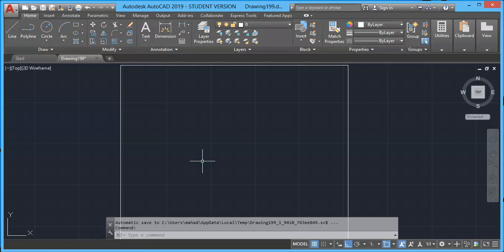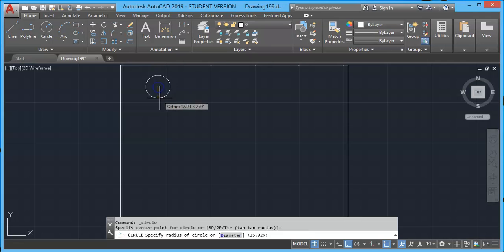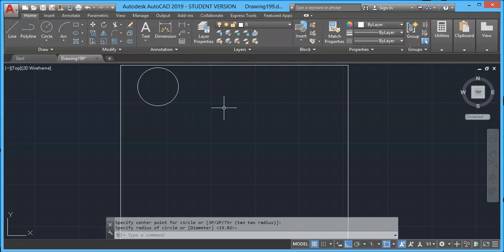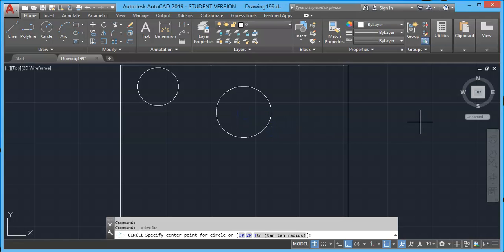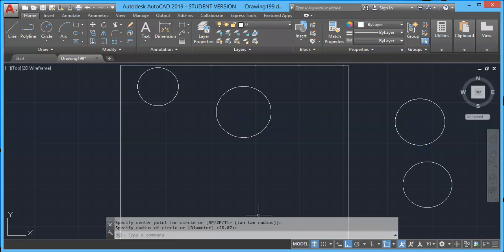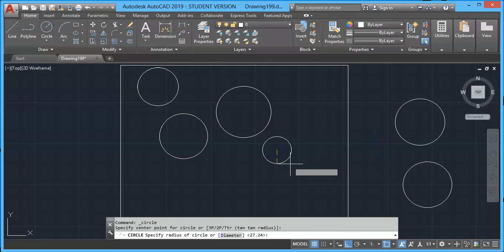At present, you can draw within limits as well as outside limits. Also, say for example, if you take a circle command, draw a circle inside limit area and outside of limits. But if you go limits command again and switch on to on option, now you will not be able to draw outside limits. In this case, you are allowed to draw within limits. So if we set limits on, we can only draw within our A4 sheet.